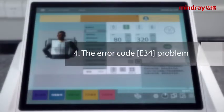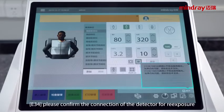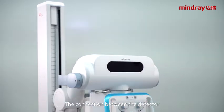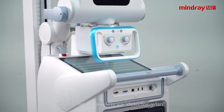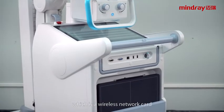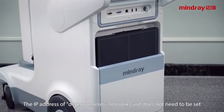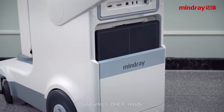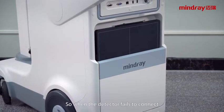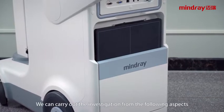The machine reported an error during exposure. Please confirm the connection of the detector for exposure. The connection between the detector and the host is wireless via the detector WLAN, which is a wireless network card. The IP address of the detector WLAN network card does not need to be set. Just select DHCP mode.